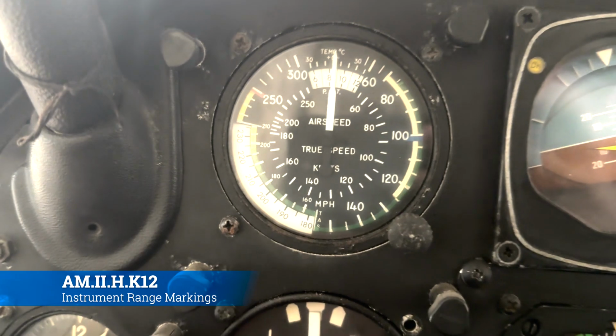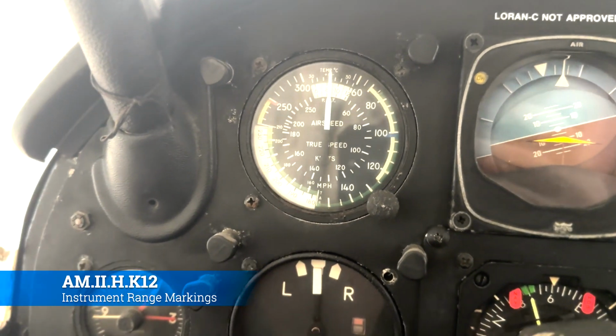Now, another thing to take into account with instruments is range markings. Range markings are going to tell us, hey, look, this is what the instrument can measure, and this is what the different markings mean, and a lot of times they're going to be color coded. One of the easiest places to see range markings is on an airspeed indicator. On an airspeed indicator, you'll have a dial that will have a circular set of numbers that indicates how many knots indicated of airspeed is hitting the airplane.